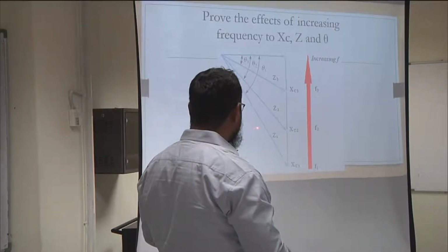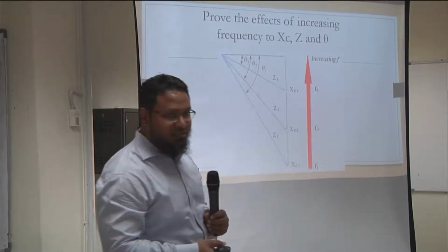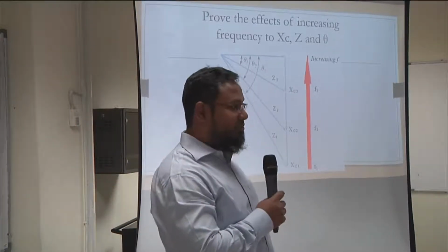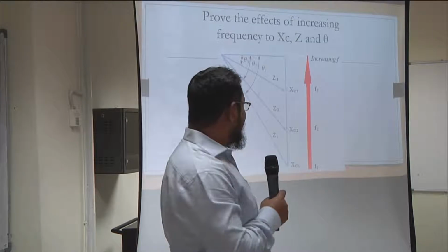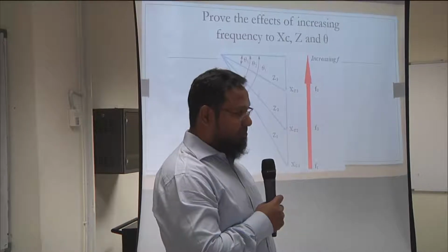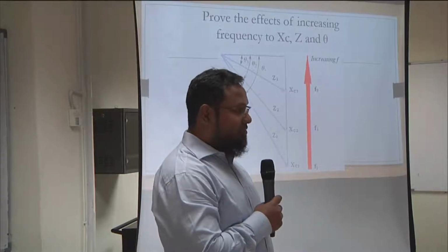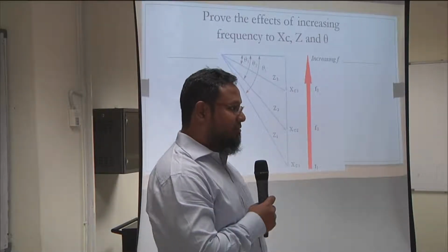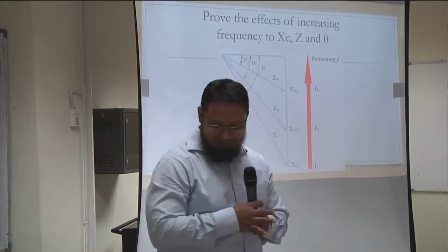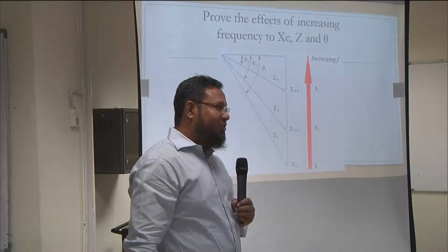Okay? So at first it was Z1, Z2, Z3. So here's a trick question for you. Hypothetically speaking, if you happen to have the frequency as infinite radians per second, what do you think is going to be the reactance from the capacitor? If omega is infinite, what do you think the reactance is going to have? The reactance is going to be 0. So in other words, the impedance is going to be 0. Impedance due to the capacitor is going to be 0.